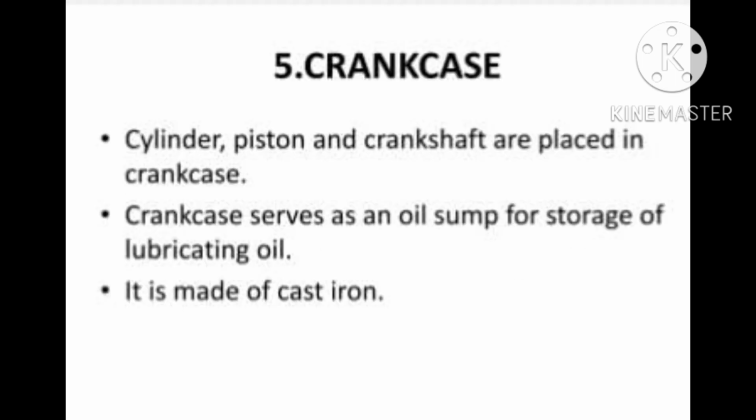Now the fifth and very important part is crankcase. So cylinder, piston and crankshaft, all these three are placed in a crankcase. Crankcase is a type of covering which covers all these accessories. So crankcase serves as an oil sump also for the storage of lubricating oil. It is generally made up of cast iron.